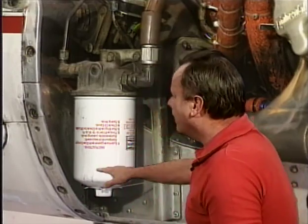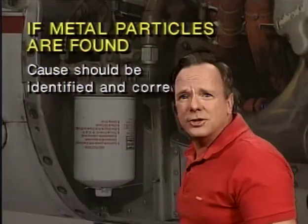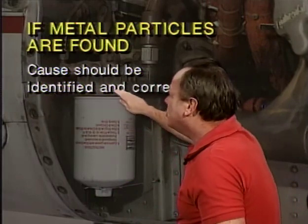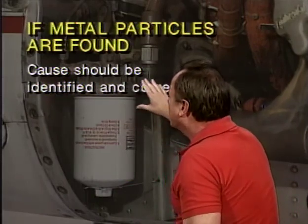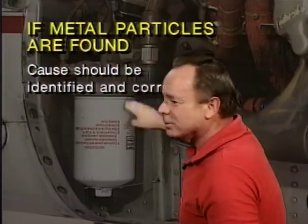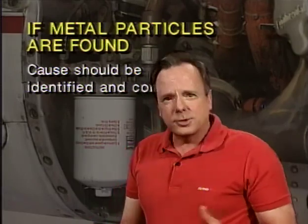Now, let's assume you've done that and you find metallic particles. The question is, what are you going to do if you find these metallic particles in the oil filter during an engine inspection? The answer is you should identify the cause and correct it before the aircraft is released for flight, because it is a big deal if metal particles are found inside the oil filter. Now, let's assume you check the oil filter and you find a deposit of small, bright metallic particles, but they're not magnetic. They don't cling to the magnetic drain plug. You could discover this in the oil sump or maybe on the oil filter, but they're not magnetic particles.